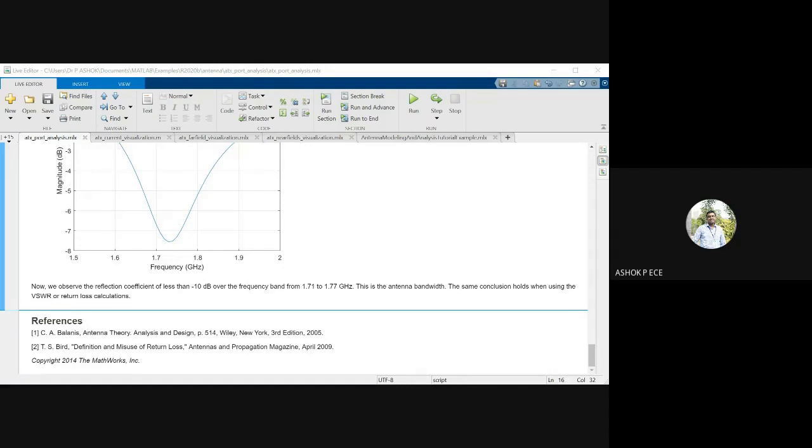As I told you yesterday, as you travel towards high frequency, you will no longer use Z, you will no longer use Y, H, A, B, C, D. You will not use all these parameters. You will be using only S parameters, because as you travel to high frequency, the factors of reflection and transmission become even more significant compared to voltage and current.